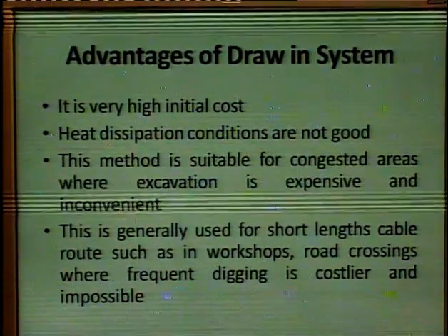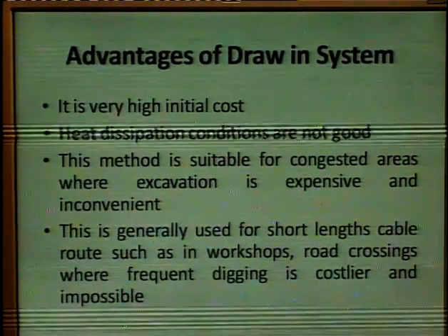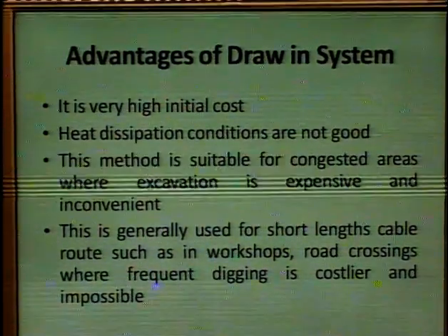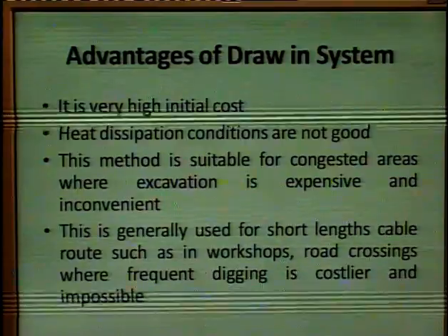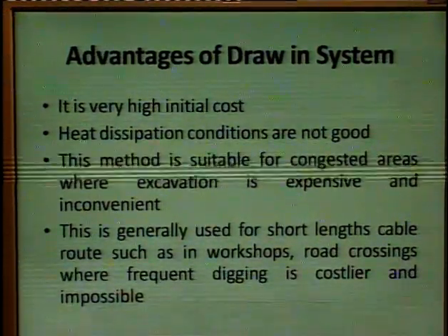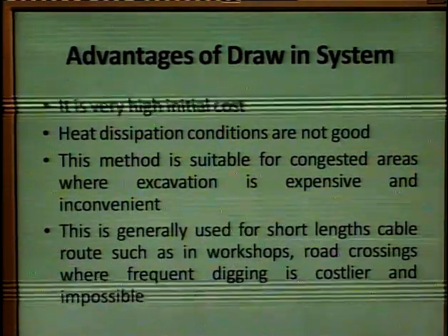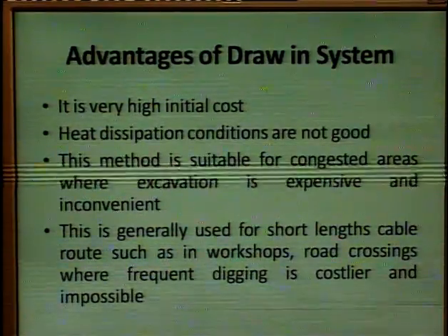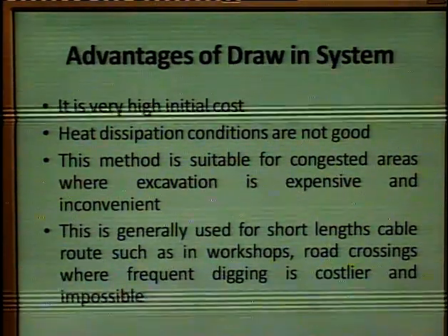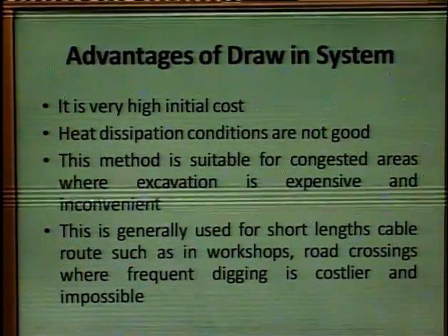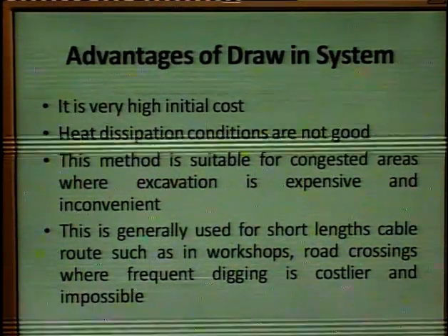So it is generally used for short length cables, such as in workshops and road crossings, where frequent digging is costlier and impossible. So you can use the draw-in system in such areas where frequent digging is not possible.